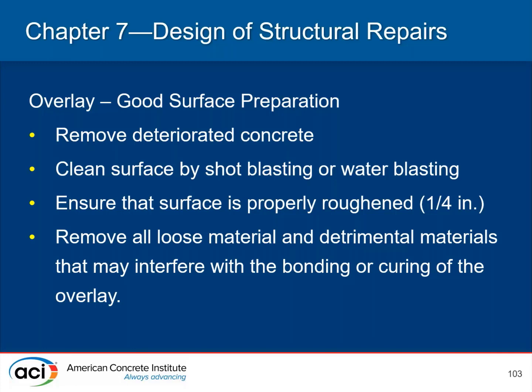So removal of all deteriorated concrete is of importance. Cleanliness of the surface to remove latents and bruised or damaged concrete, and then ensuring that the surface is properly roughened to that required by specifications. The profile can impact, again going back to that shear capacity of the bond, profile of the surface, as well as how clean it is and how sound it is, all impacts that shear capacity. So removal of all loose material and detrimental materials that interfere with bonding or curing of the overlay is of critical importance.